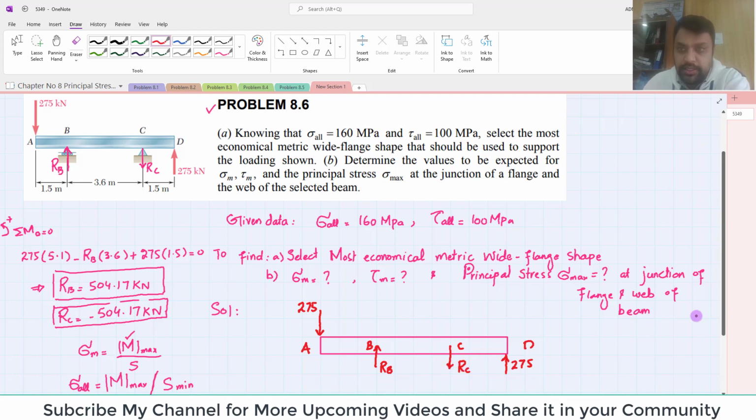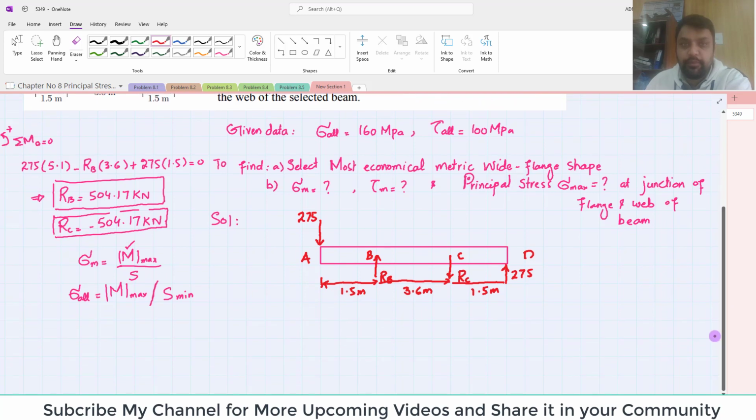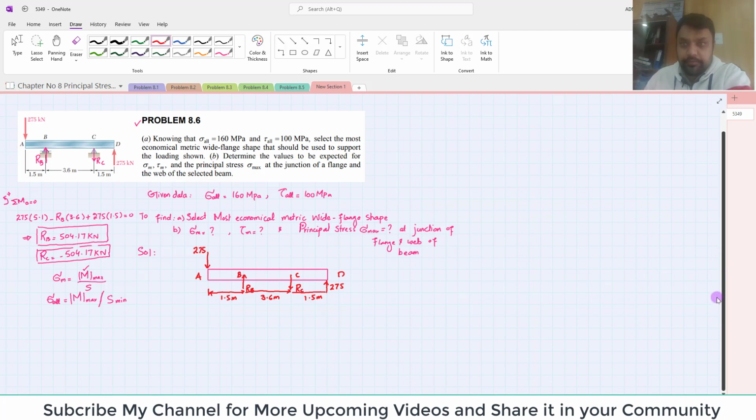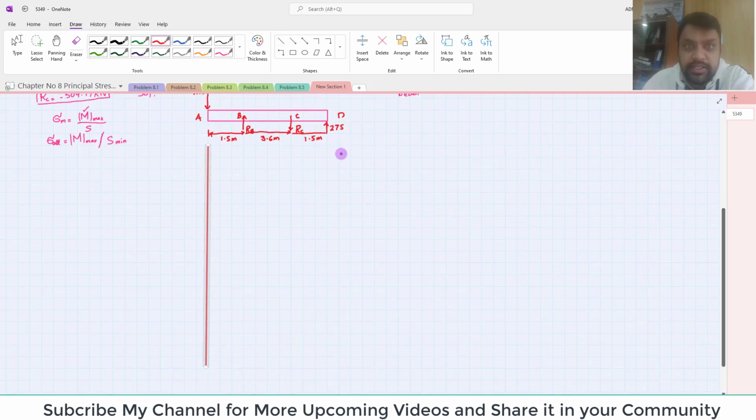The distances between them are shown over here. You can see this distance is 1.5 meter. The distance between B and C is 3.6 meter, and again this distance is 1.5 meter. So we will draw the shear force and bending moment diagram. I will show you how to find it. We have to draw the lines from these edges, and similarly a second line from this end.